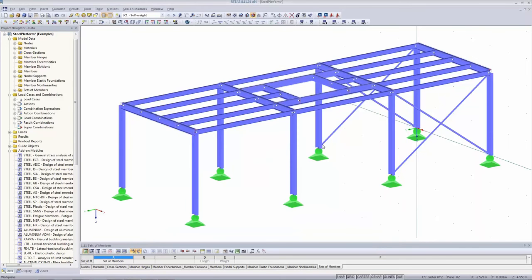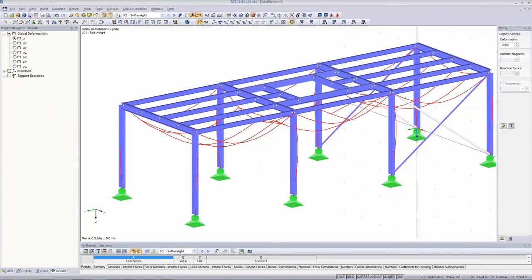That's just due to this kind of special load case, that the loads are just acting in a vertical direction. If you would combine it with some loads in the horizontal direction, we wouldn't have the same problem. But here, now I double check, the calculation is working. Yes, you see now the deformation, the global deformation is 0.5 millimeter, just self-weight, and you also see the failing tension members, which are colorless now. Okay, so we double checked our model, and we can go ahead defining more loads.